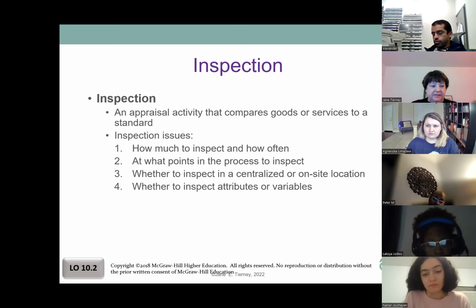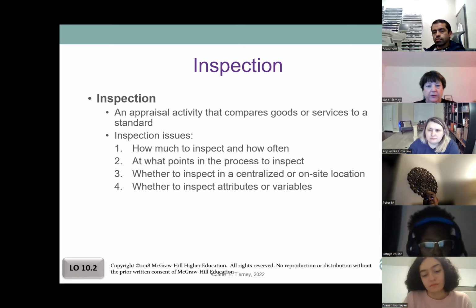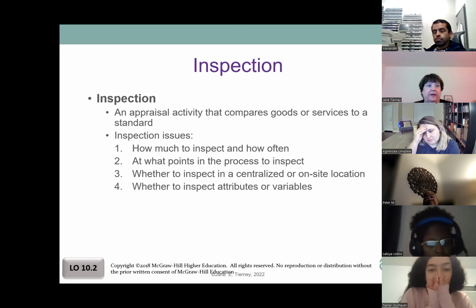If we needed 6 inches and we poured an 8-inch foundation, we might say, oh, this is probably going to be okay. It's a little more than we needed. We can live with that. But you have to weigh all those things against everything else. What is my specification? And then what is my actual value? So that's going to tell us that we need to inspect that.